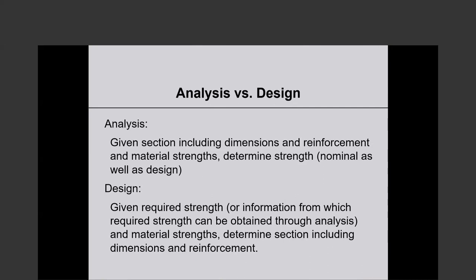Okay. Now, analysis versus design. What's the difference? Analysis is, given a section, including dimensions and reinforcement and material strengths, determine strength. That's what we were doing so far. We were analyzing. What is design?